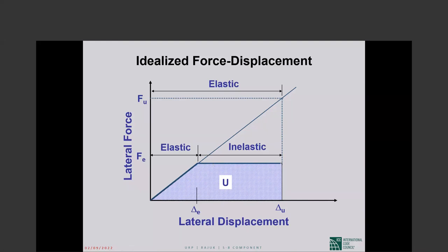The damage has to be repaired, but more importantly, we do not want our structure to collapse because these inelastic deformations are too large. So the inelastic deformations must be within the inelastic deformation capacity of the structure. Inelastic deformation capacity is the range of inelastic displacements over which factored gravity loads can be sustained.